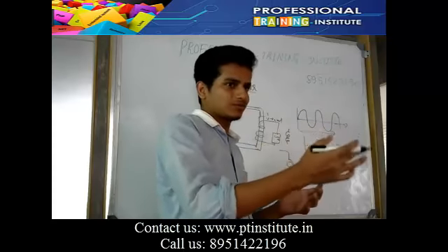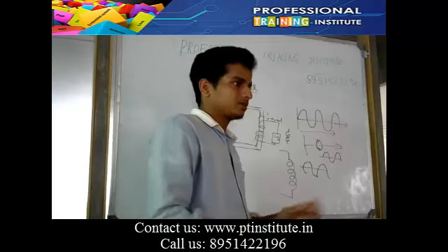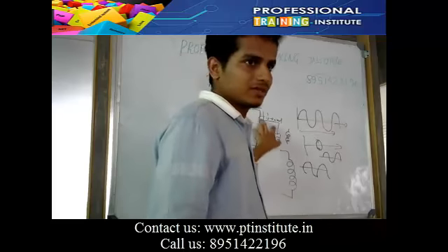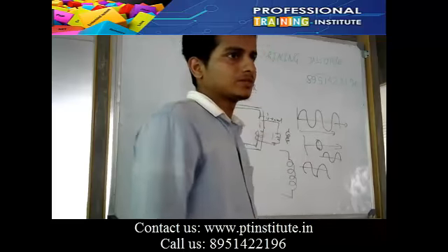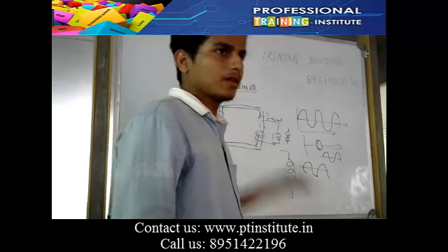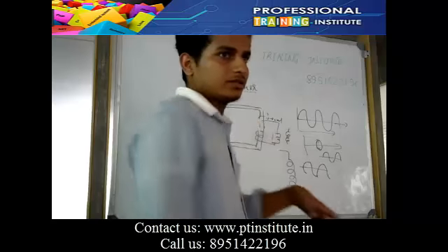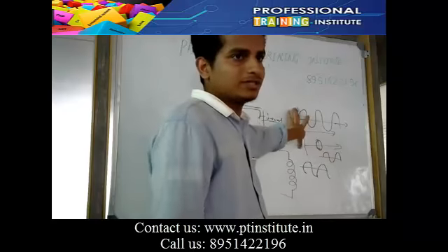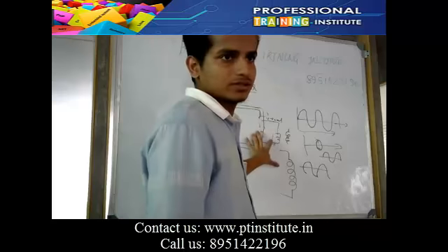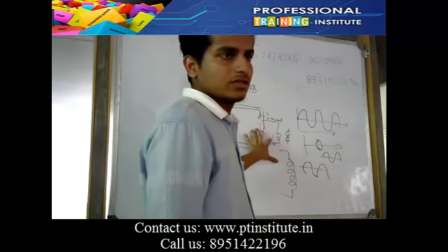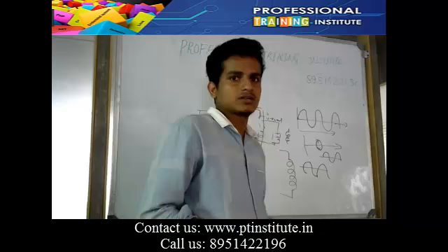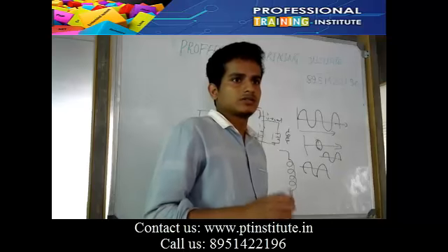Flux will cut more because of the field. In the secondary, there is a greater number of turns, so this is actually stepping up. If we want a higher voltage, we have to increase the number of turns. So if we increase the number of turns, will it be step up or step down? Step up.